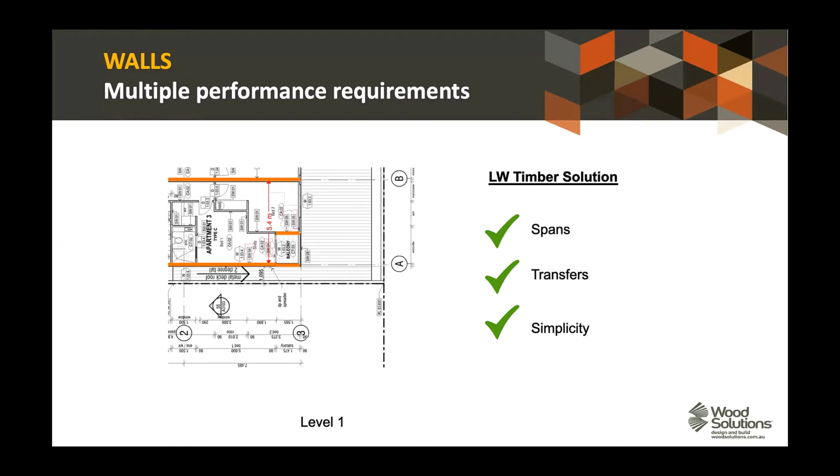We need to think about where we have load-bearing walls, where we have walls that are non-load-bearing but will be part of our stability system, and where we have a requirement, either acoustically or otherwise, for separated skins of walls.